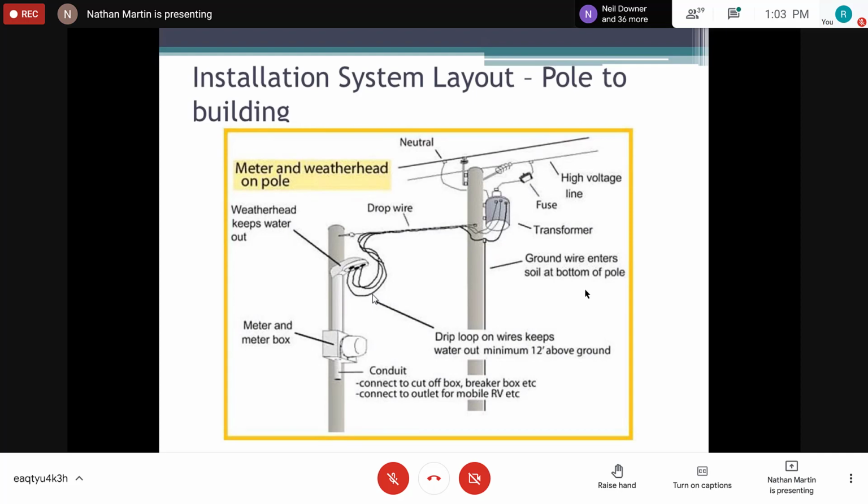And this is why you need to have the cable route, because if you are using a backhoe, which is what they use rather than manpower, when the backhoe makes one scoop with the bucket, it basically goes below the desired depth and busts up any cable or any pipe or anything like that, you know. So again, that's why it's best to have your cable route diagram.